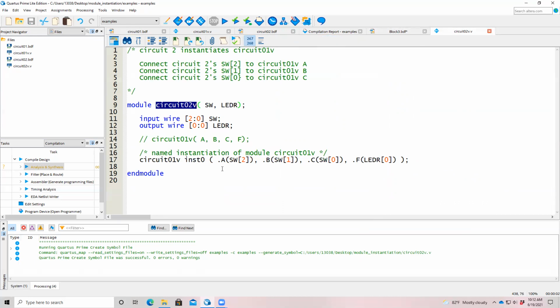I'll create a system and I'll use block symbols. I'll draw wires from one to the other so I can have an idea of how I want to wire these together. And of course, the longer I work, the more I can see it in my head, and I don't have to do that. But I find a lot of times, to make sure that I'm connecting things correctly, especially if I'm getting tired, drawing a picture always helps.